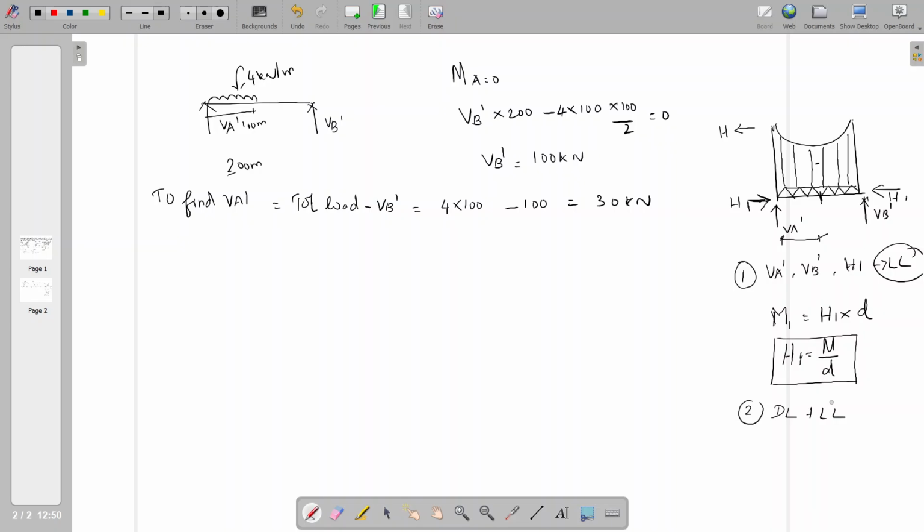Here there are two situations. If you convert the dead load into, actually the load is as an area load, that is if you have some load in kilonewton per meter, the live load is also in kilonewton per meter, it is converted as an equivalent UDL throughout the cable.